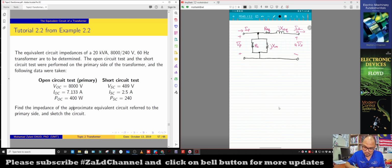This is the approximate equivalent circuit referred to the primary side. If you refer the equivalent circuit to the primary side, the parallel branch, which is RC and JXM here, can be determined by using the turns ratio.